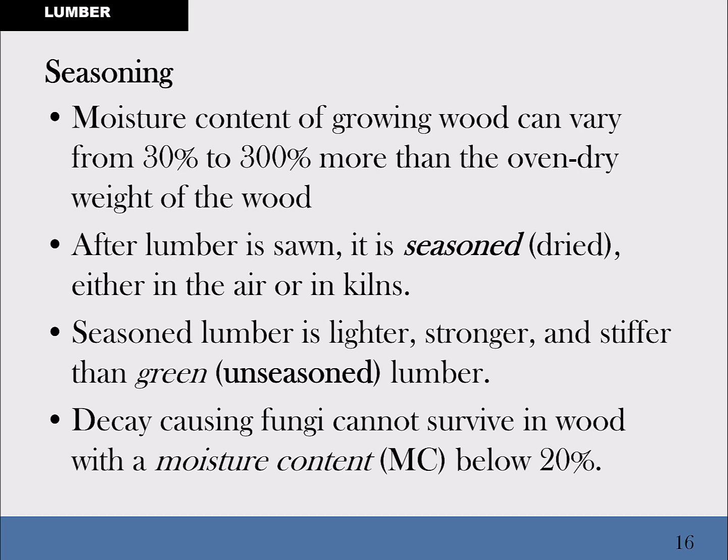But the basic thing we do to protect lumber is to make sure it's dry before we ever start framing. First of all, so you don't attract these critters, and you want to keep it dry after you've built it. So you don't want any moisture finding its way soaking into the wood. You need your wood to stay dry.